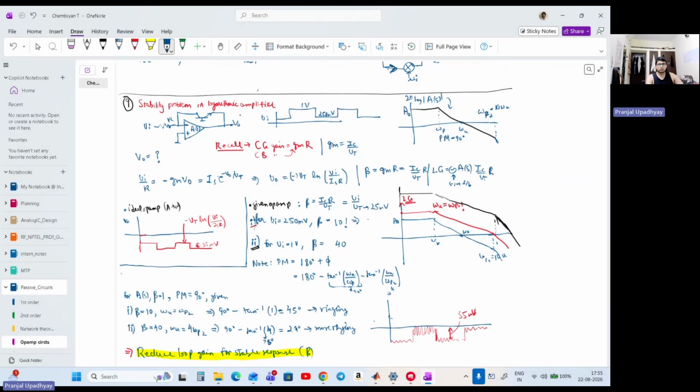input. Yeah. So here this problem is a stability problem, and what it is trying to say is that this op amp is real, which means it has a real gain, it has some poles, and this is the pole which is given, and this op amp is basically modeled by two poles actually, and the second pole is far away. It's 10 times the unity crossover frequency, and it has a dominant pole at omega p. It has a DC gain of A naught.